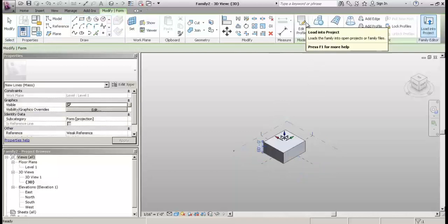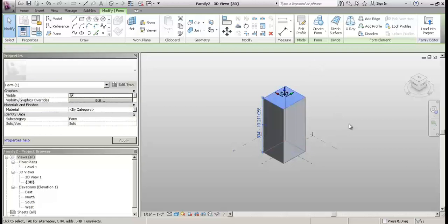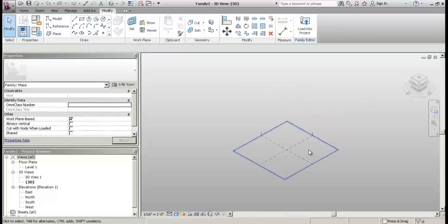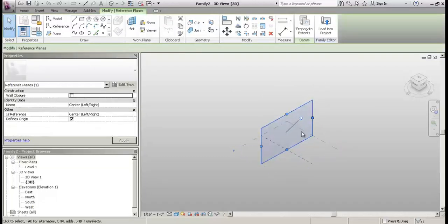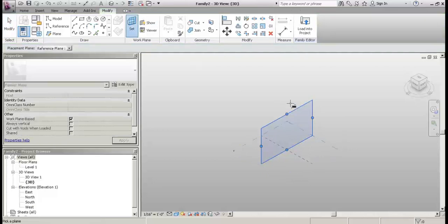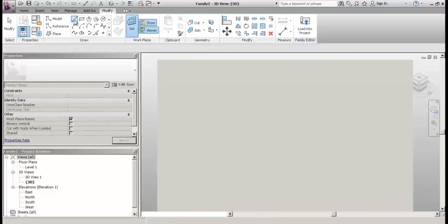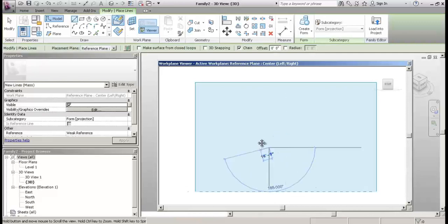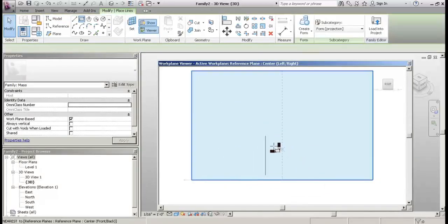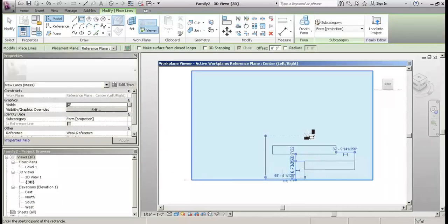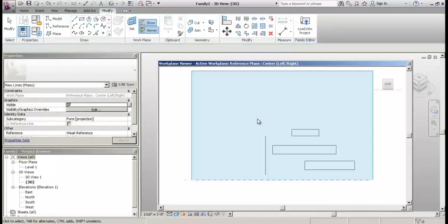So if I wanted to make an extrusion, I make a rectangle, and then I have my box. If I wanted to make a revolve, let's undo what we just did here. If I wanted to do a revolve command, I can set my work plane to that piece. And I'll show my work plane so I know that I'm on that. Then I'll open my viewer so I know I'm up and down. I'll draw in my revolve axis, right, and then I'll draw in my actual cross section. Right, so let's say that was my cross section, a series of circular floating planes.